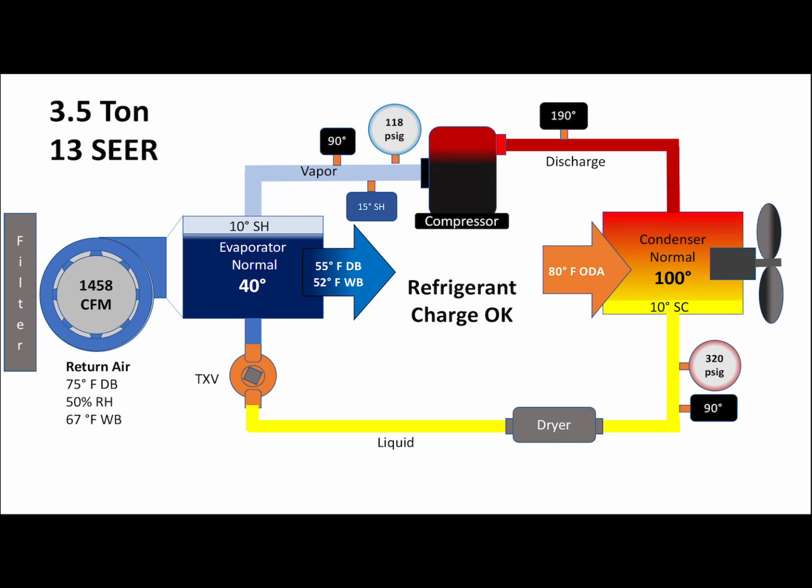And then that liquid's cooled down to, in this case, I think it said 90 degree liquid. So we're 100 degrees outdoors, we have 90 degree liquid, that's 10 degrees of approach, okay? Or excuse me, it's 100 degree saturation temp. We have 90 degree liquid and 80 degree outdoor air. So it's 10 degrees of approach, right? And then, back to the TXV and back around again.